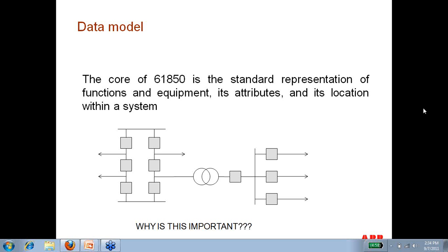I guess what I could say is this, and I can only assume that what we're referring to is when we look at logical nodes and the information that's available within a logical node, there's something called data objects and data attributes, which are essentially pieces of information that are associated with that particular logical node. Some of those are mandatory. Some of those are optional. All IEDs, if they support a particular logical node, have to support all the mandatory elements inside that logical node. However, the ones that are optional are optional.